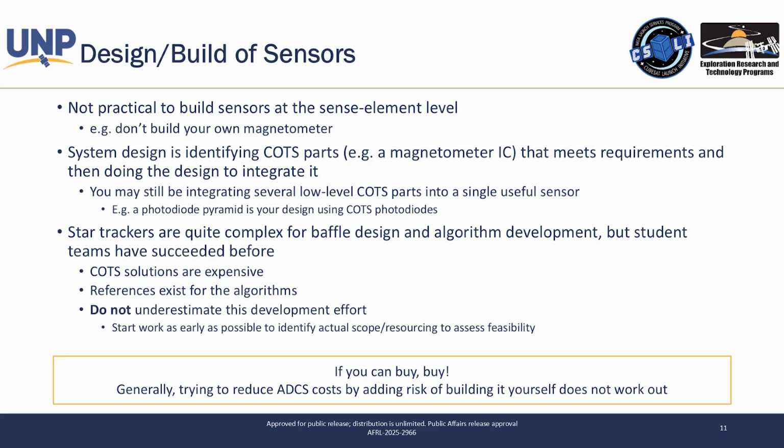So you always need a second measurement point to be able to lock in and know how you're oriented. With that said, you need two independent measurements to know your attitude. If you don't really care about knowing your attitude, then yeah, you don't necessarily need all these sensors.